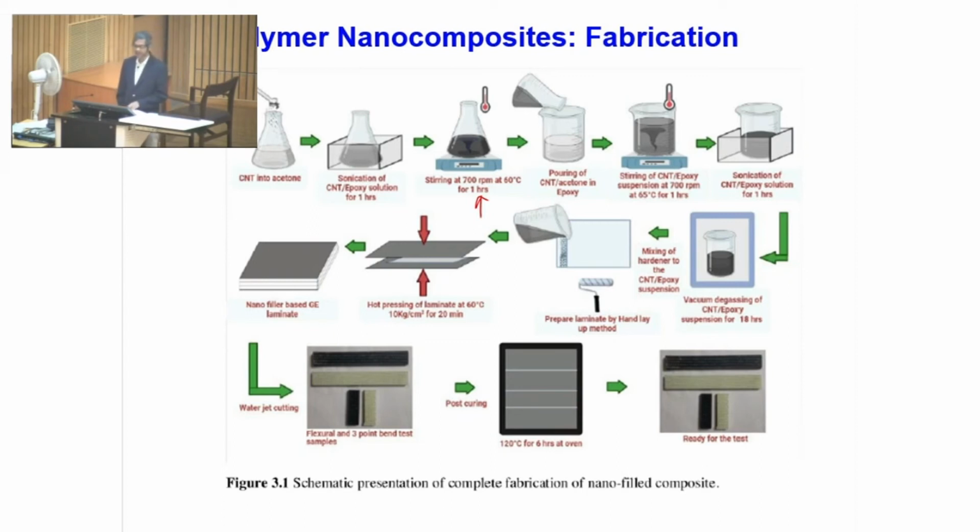Nanoparticles can also significantly affect, as I discussed already, the Tg or the glass transition temperature. Typically this occurs because nanoparticles influence the mobility of the polymer chains due to bonding between the particles and the polymer, and even the bridging to the polymer. Okay. So in some cases, a depression in the Tg is observed, which is not good news. However, in many cases, the Tg increases a lot.